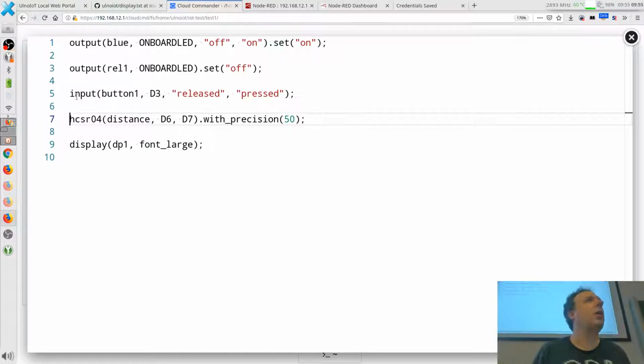But it's actually not a high range, isn't it? It's just for 3 meters? 3-4 meters, yeah. Same as the time of flight sensor we have. If you want to measure longer, you need a real laser and reception. This device is €2. Then we have a time of flight sensor, which is a little laser and which can measure that back, which is around €10.